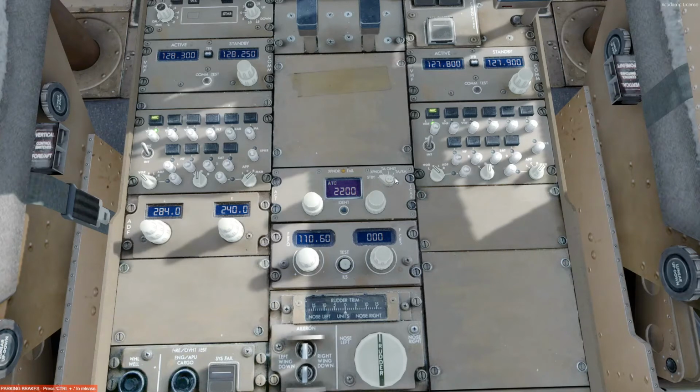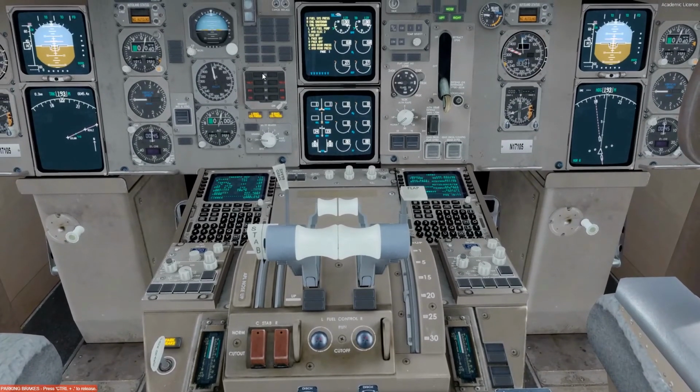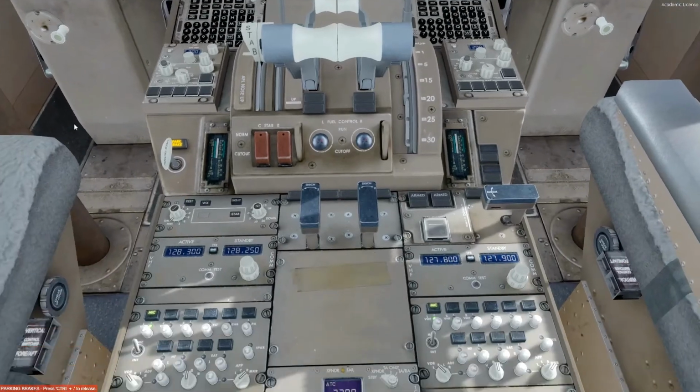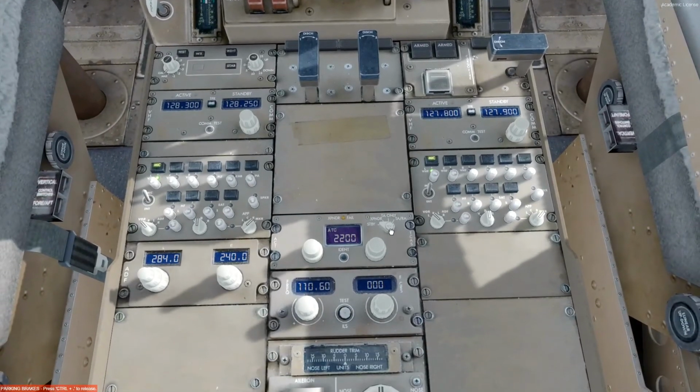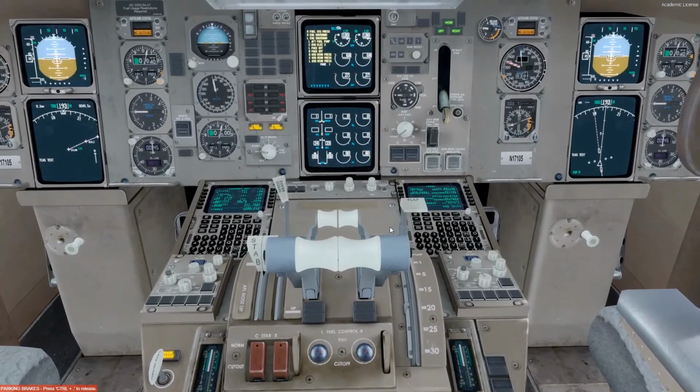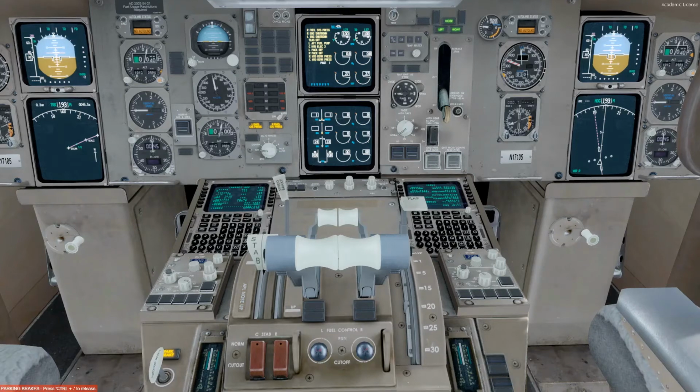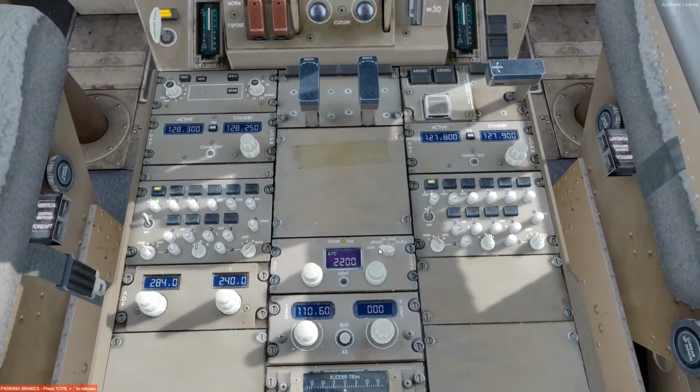It also is used to control a system called TCAS, or Traffic Collision Avoidance System, and that detects planes in front of the aircraft, and if they come too close, it'll tell the pilots about any evasive action they will need to take. So we're going to need to test the system, make sure it works. TCAS test. Pass. TCAS seems to be working. We can turn on the transponder.